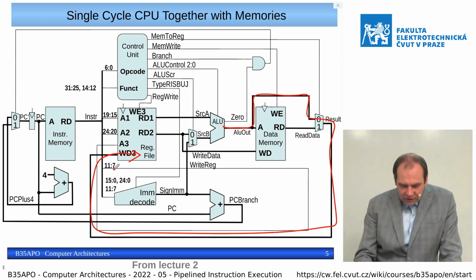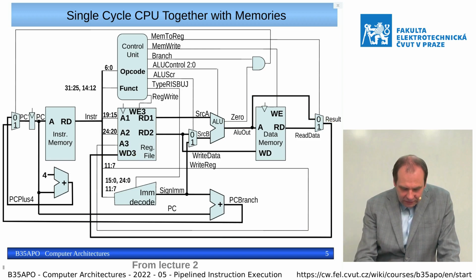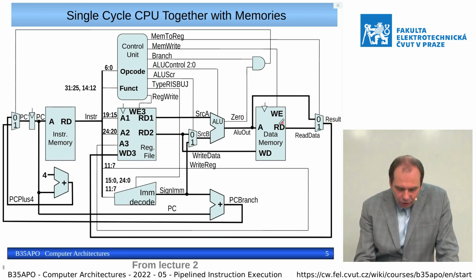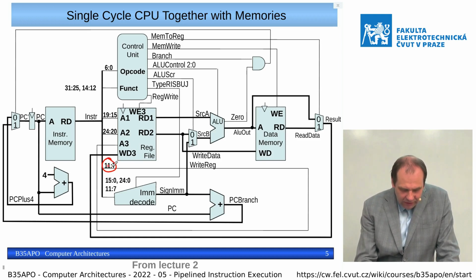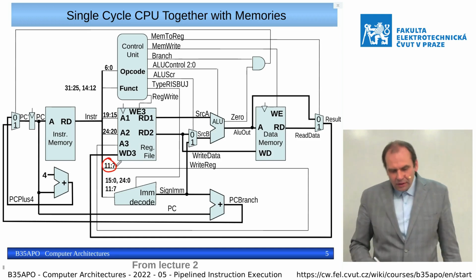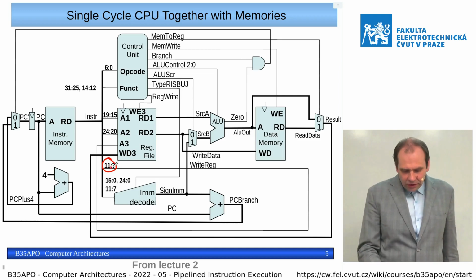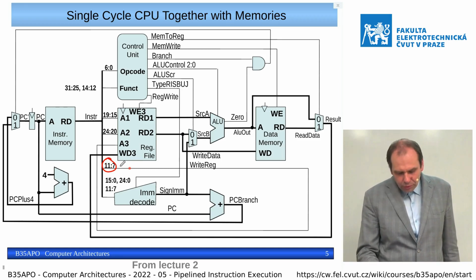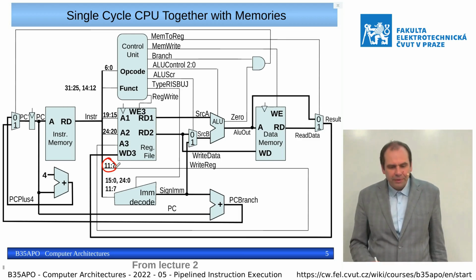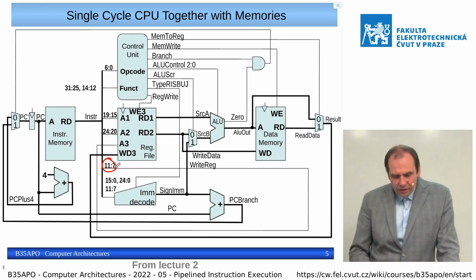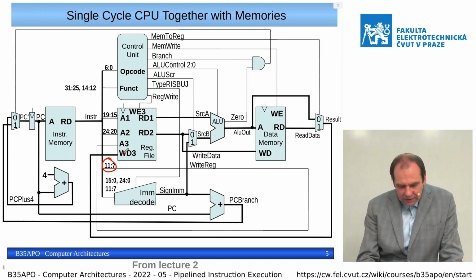And the register to which we want to pass computed data or data read from the memory is selected by bits 11 to 7. We use this notation from the higher value down to the lower one because it is how we use it in, for example, VHDL or some other hardware description language.